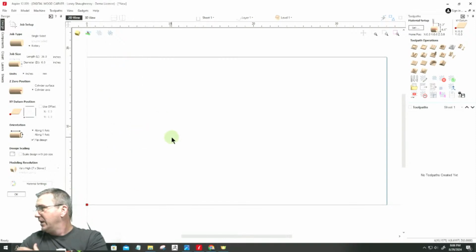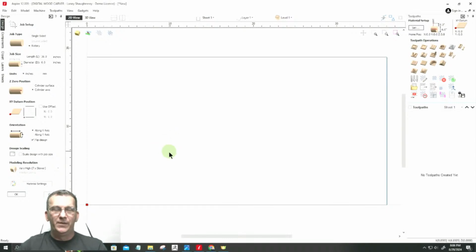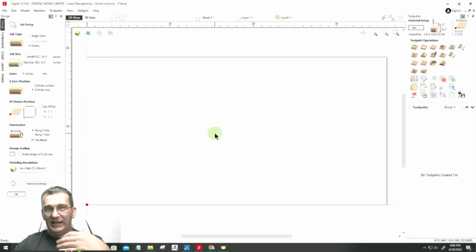All right. So in your Vectric software, in the case of this, it's a rotary job. Now, your rotary job may rotate around your x-axis, meaning that the length of the spindle runs along the x-axis of your CNC. And when the Y or the A rotates, it's rotating across that x-axis.